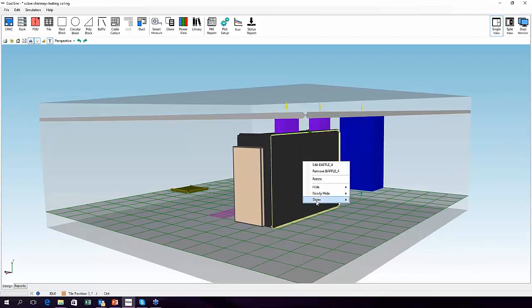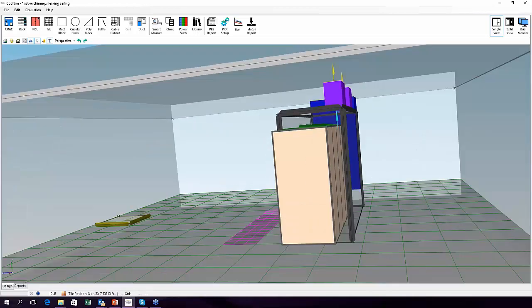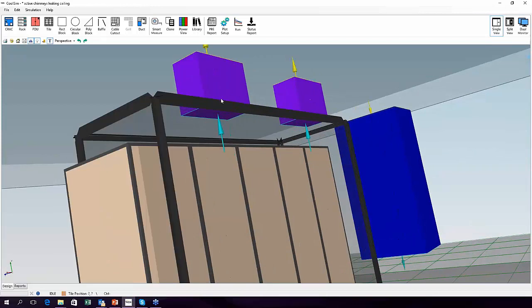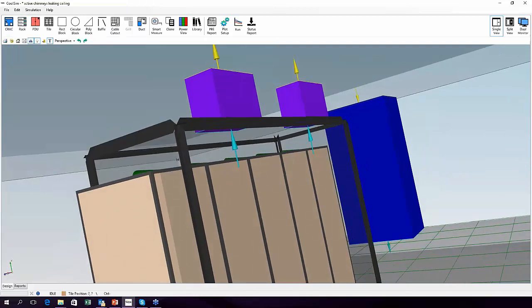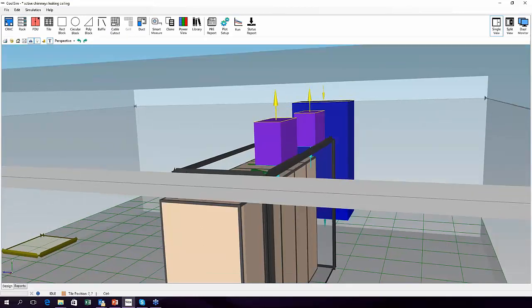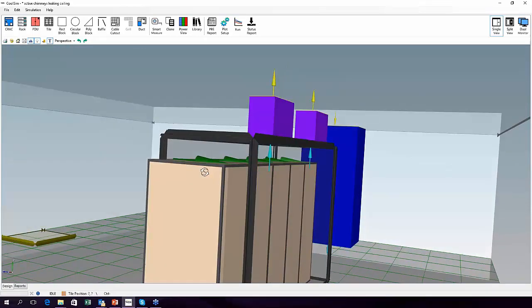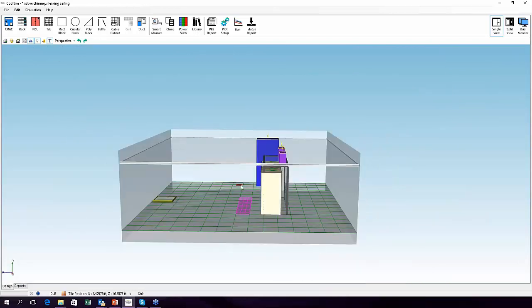If we make these transparent, nearly hide baffles, you'll see that they're sitting in there and then have these active chimneys that are poking down through. You can see again, these are PDU objects. They're probably set to allow air to come through them at a high rate. Yep, 1 kilowatt, 1500 CFM. So that's a factor of 10 more than normal. These are acting as fans, but they are producing a little heat, which is realistic. They're sucking the hot air out of the contained area and up into the ceiling. And there's a cable cutout.